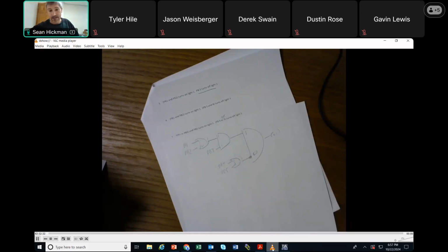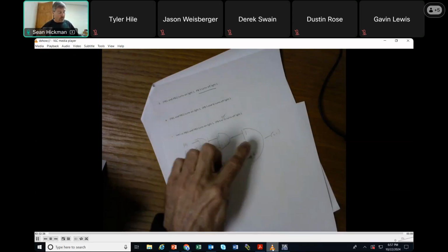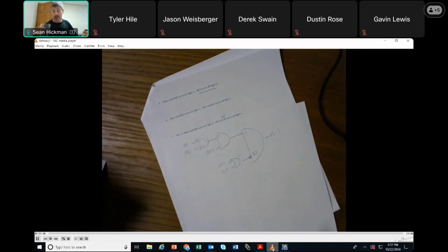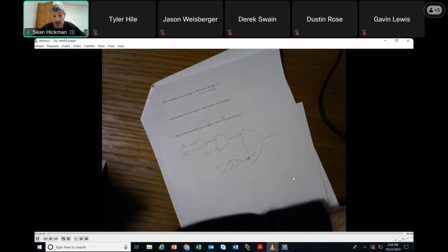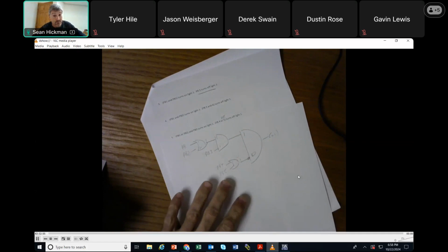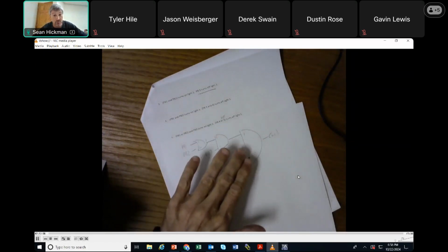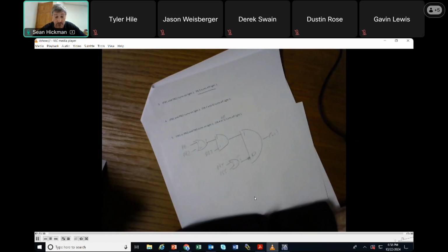So you just got to kind of keep building them up in your head just to think about, what if I push the button? What's going to open? What's going to close? And the thing is, if you were programming this in ladder logic, you still need to build it up in your head and look at the logic and say, all right, if I push this button, what's opening, what's closing, okay? And the other thing is you could look at it on the screen. When you program Boolean, you'll see what's coming true, what's green, and what's not, all right? That's the beauty of it. All right.